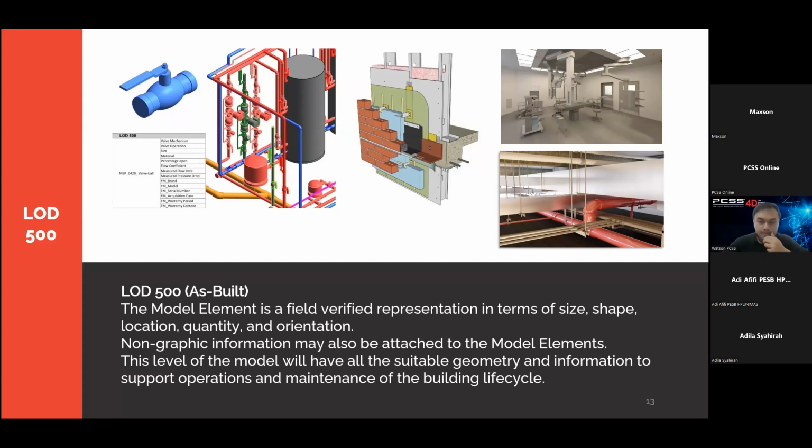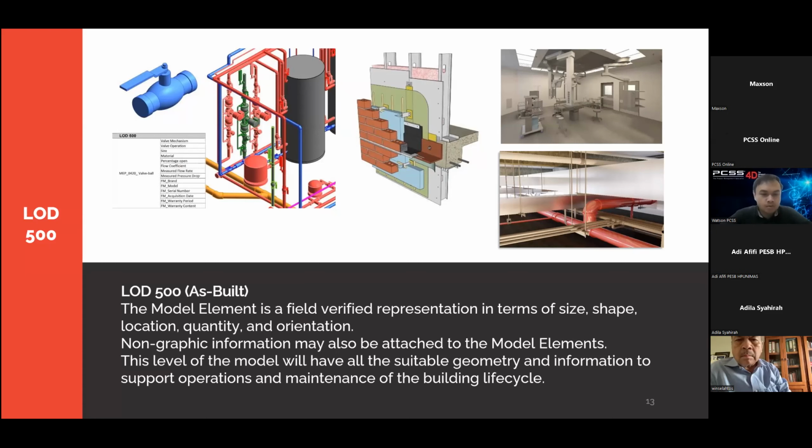But bear in mind that if a project wants to have facility management or wants to have operation and maintenance as a BIM use in that building, then LOD 500 plays a very important role because it's not just an update of field verified model, but it actually has additional information. Most probably they are non-graphical information into the parameters that are related to facility management.